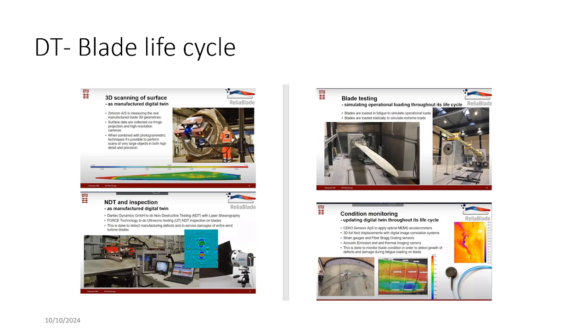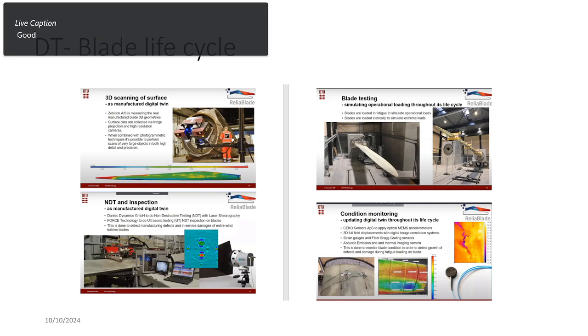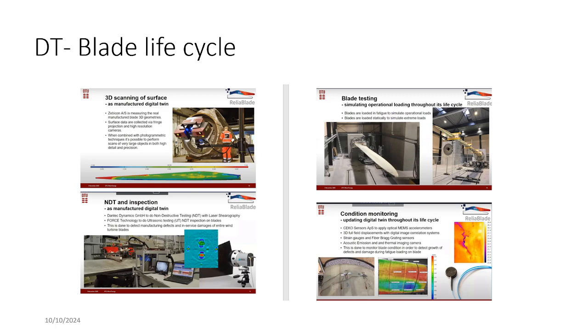Fatigue is one, that is, if you want to break an aluminum rod, let us say. If you want to break it fast, you have to bend it fully 180 degrees up and down. That means you are giving extreme tension and extreme compression to the fiber of the rod. Then you can break the aluminum rod in 10 cycles. Suppose you don't bend it 180 degrees, bend it only so much, it will go for 100 cycles.